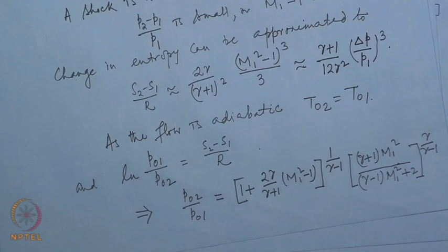Since change in entropy is directly proportional to change in total pressure, the change in total pressure is also of third order in shock strength.